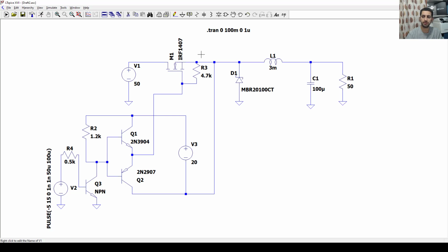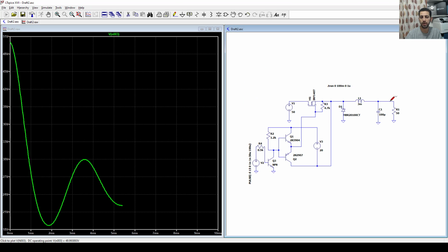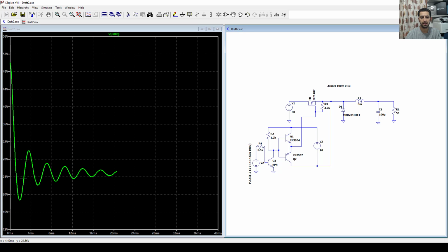So far we have built this buck converter, and we can control the duty cycle by this PWM signal, and the output voltage will change. So we have here 50% duty cycle, and I think the output will be going to the 25 volts. So let's now just wait, and I think, yeah, it's going there. Okay, and this is the transient here, and we are not actually going to set the transient. So the steady state will be going to 25 volt.